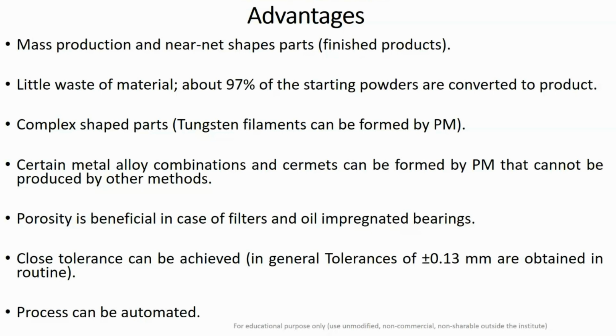And what is the application of this porosity? Basically, it holds the lubricant in the pores, and whenever these bearings are compressed under loading conditions, the trapped lubricant comes out from the pores and causes automatic lubrication. So this is a very brief discussion about oil impregnated bearings or bushings. You can learn a lot on the internet, and I will try to share different videos with you.